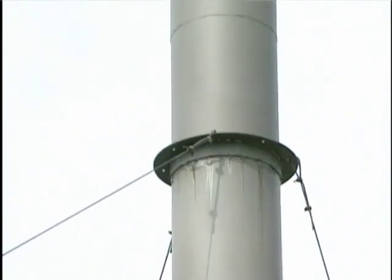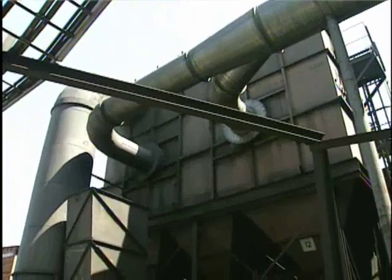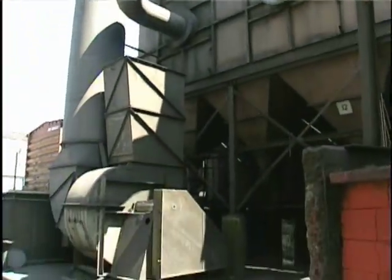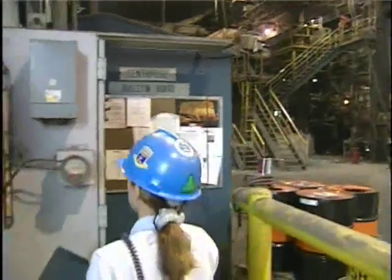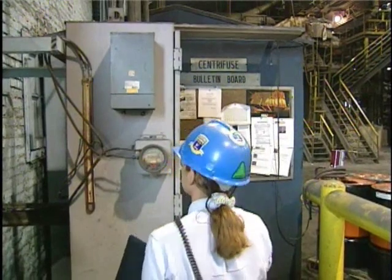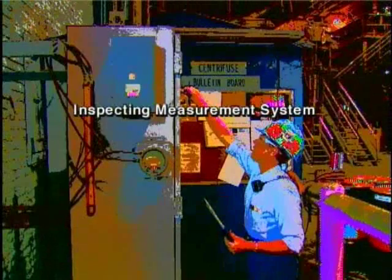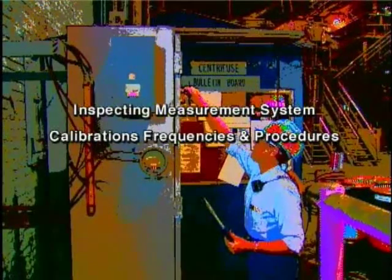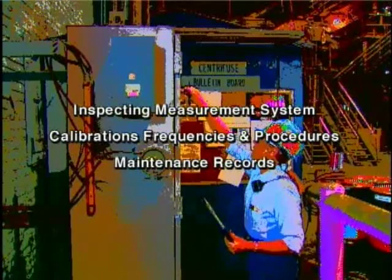The most direct indicator of the performance of a fabric filter is the opacity of the discharged gas stream. An increase in average opacity from the baseline value provides an early indication of developing problems. If there is an opacity monitor, past trends in opacity should be evaluated. Before doing so, the adequacy of the data should be evaluated by inspecting the condition and integrity of the measurement system and checking the calibration frequencies and procedures and the maintenance records for the instrument.